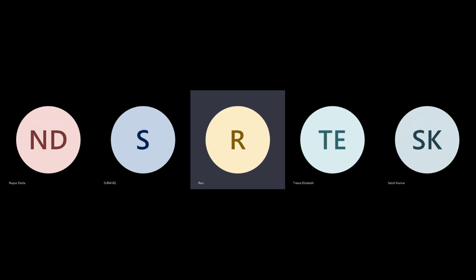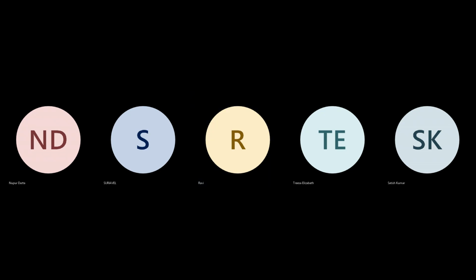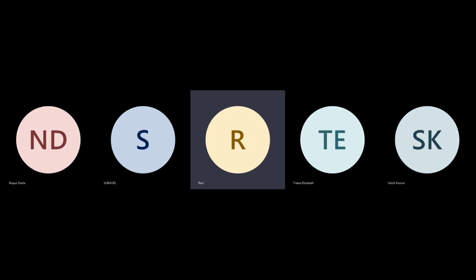But it became more obvious in 90 nanometer and below. Even the lower temperature corner became a critical path. In higher technology, at higher temperature the cell delay will be more. But even at the lower temperature, because of the diffusion problem, it started to increase the delay of the cell.